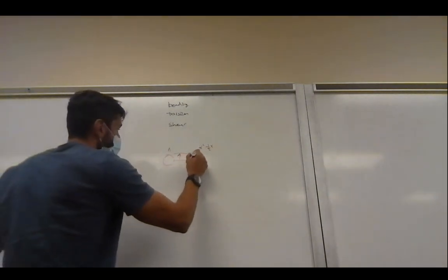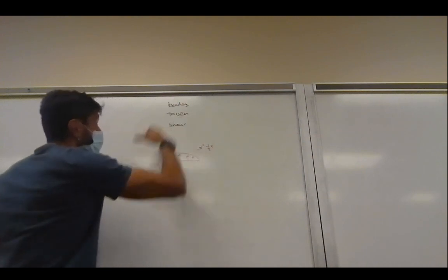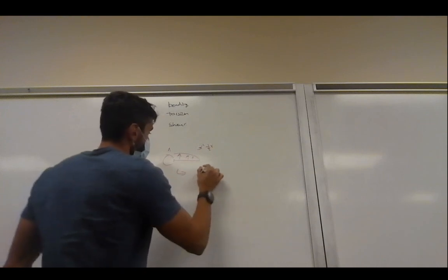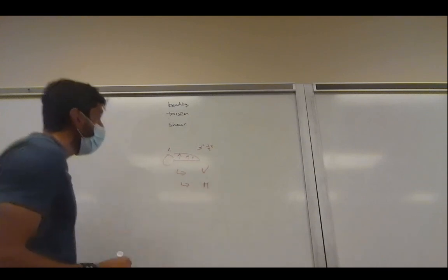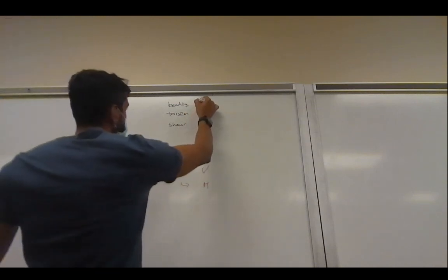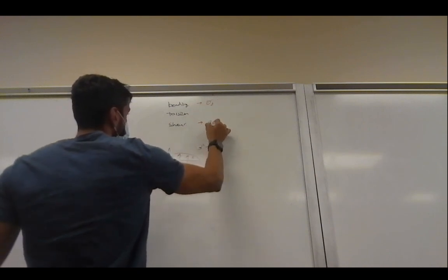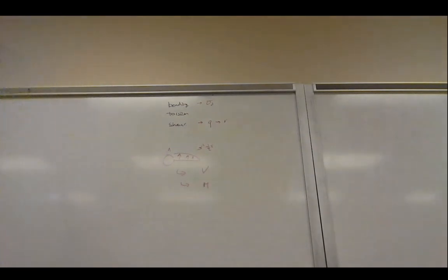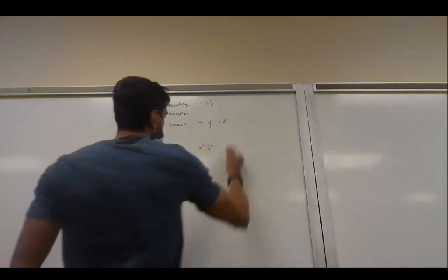What you can do then, if you want to calculate the shear flows and all that stuff, is create a shear force diagram and a moment diagram, and then based on the shear force and moment diagram, you can calculate whatever the bending moment component is, at any location, and what the shear flow is, and therefore the shear stresses.